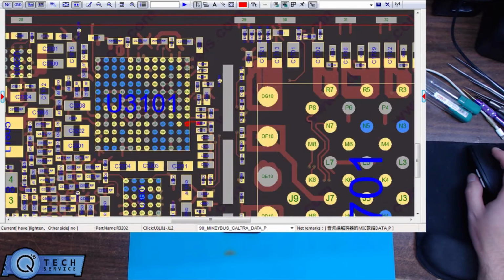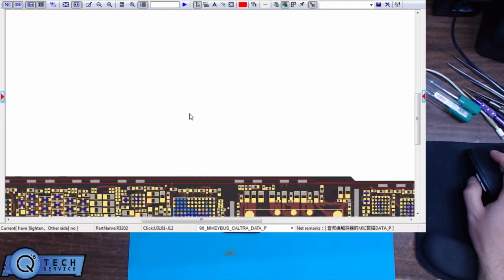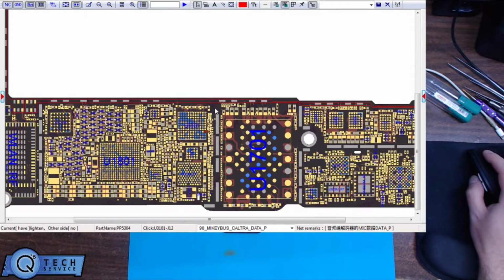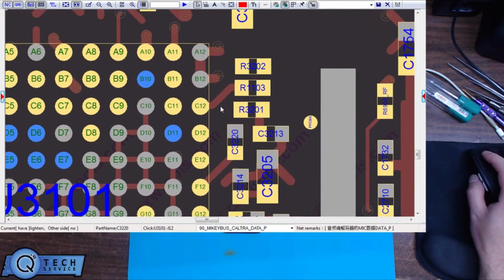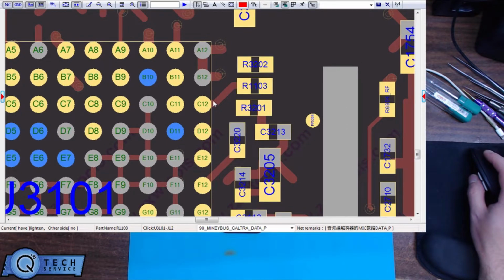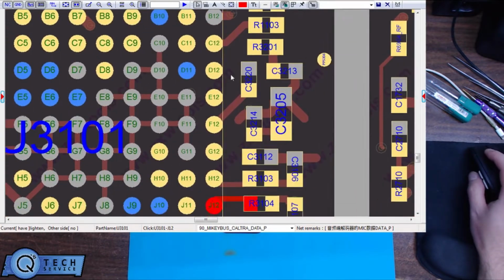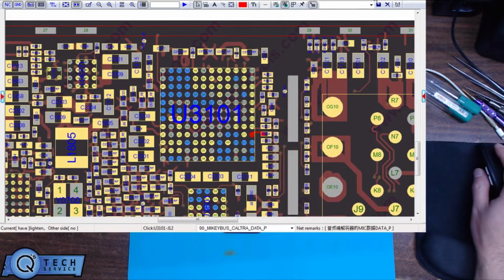I mean, the board is more prone to being bent right there in that area because of a weak spot. But it's basically why the defect is here, is how the pads just cut and turn right here at the chip, which you can see in other videos that I have too. But let's get started.